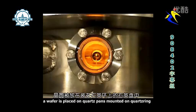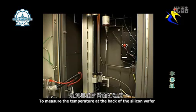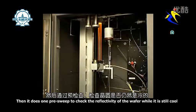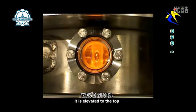Inside the furnace, a wafer is placed on quartz pins mounted on a quartz ring. A pyrometer head focuses straight up the elevator tube to measure the temperature of the back of the silicon wafer. Then it does one pre-sweep to check the reflectivity of the wafer while it is still cool. Once the wafer measures 800 degrees, it is elevated to the top.